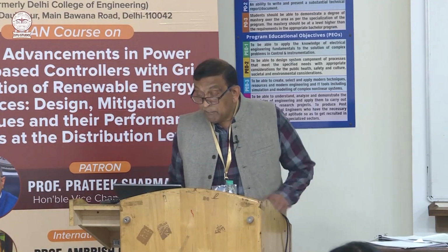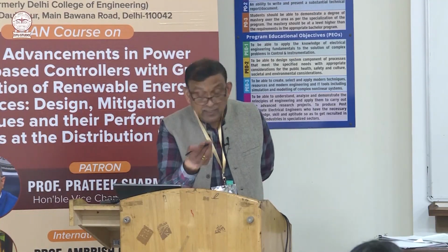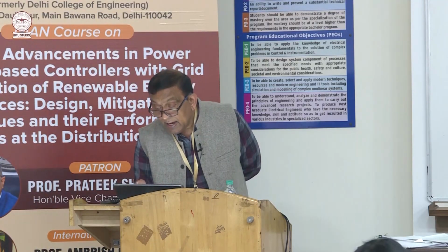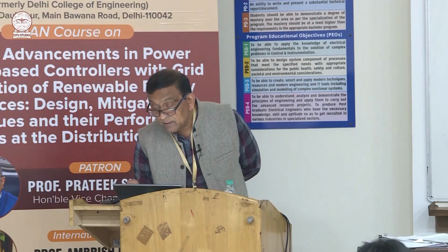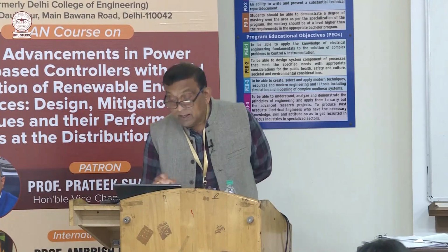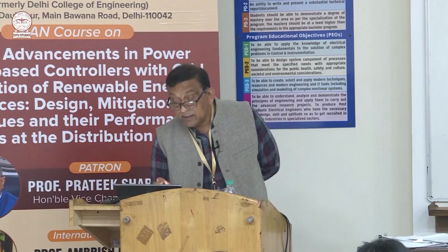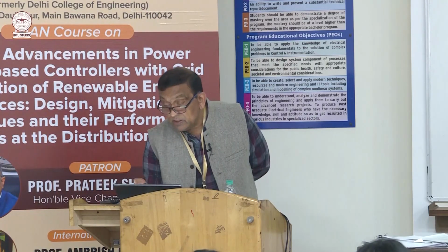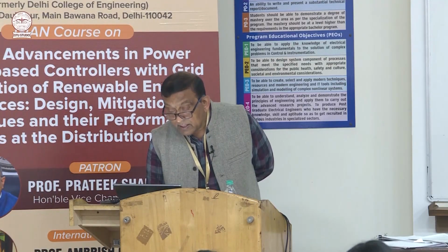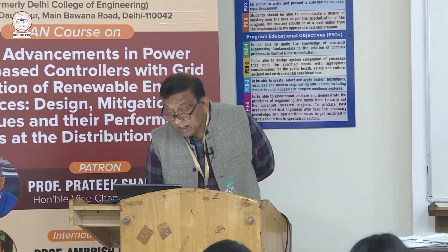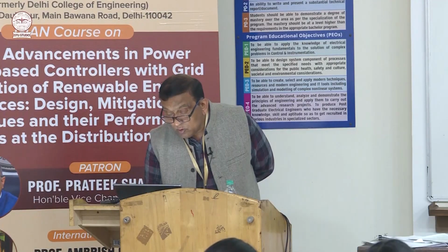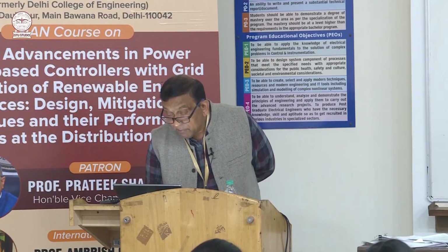See, this is the example which we have already seen. This is the DY1 transformer and this is the DD0 transformer. Just now we discussed this, right? So you have identical equal loads here on the side, with the transformer DY1 and DD0. If you write the equation of current here, this current is proportional to the fundamental, 5th harmonic, 7th harmonic, 11th harmonic, and if you write I2, it is proportional to these things, but see the sign.